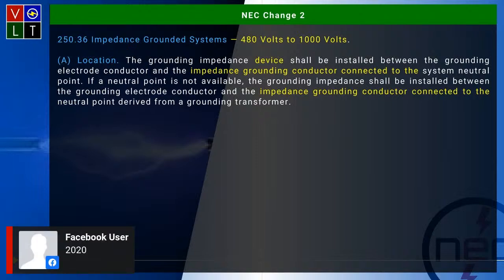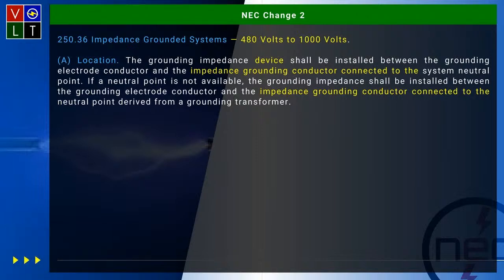Now, the other thing I will point out, you also can have an isolated equipment ground that will also count in there. That's not part of that calculation for the equipment grounding conductors. Okay, cool. You can pick all that information up over in 314.16(B)(5), and that happened last cycle in the 2020 NEC.